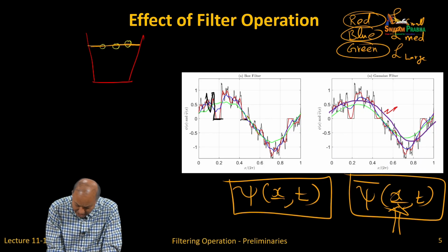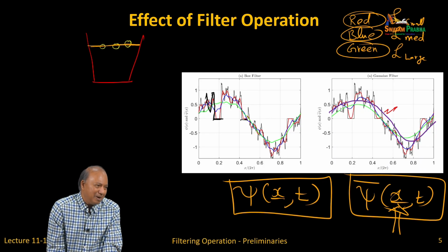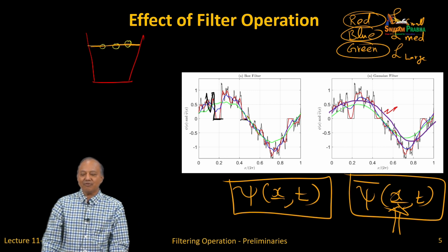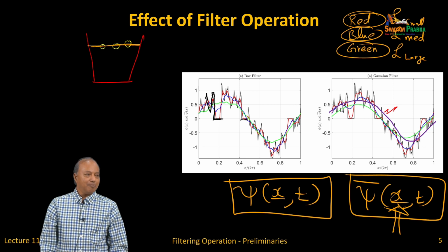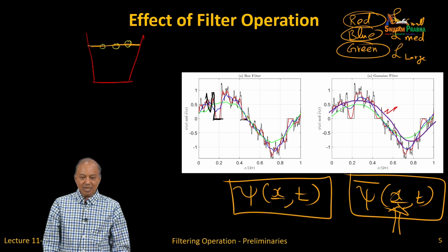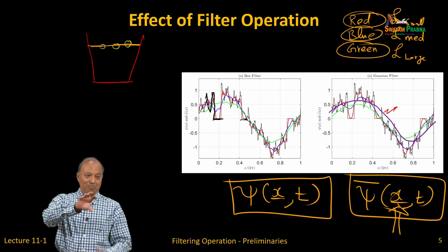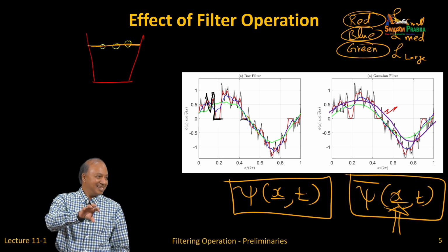So follow-up question with regards to filter size. We have to keep in mind the particle size as well, because if the filter size is somewhat comparable to the particle size, then our averaging models won't work, right? For Euler, I'll jump to Euler. Yeah, you are right. Your averaging volume is better if it is bigger than the particle, because otherwise what happens is, think of this, if your filter size is of the order of your particle, your grid will be so big that your particle is so big in it, right?